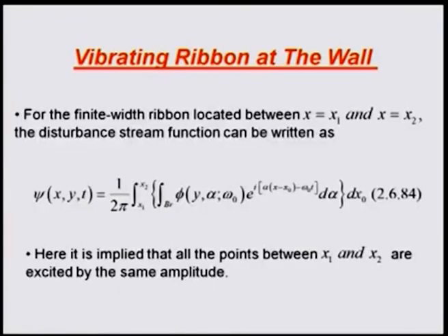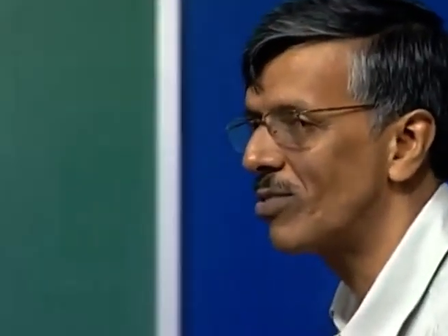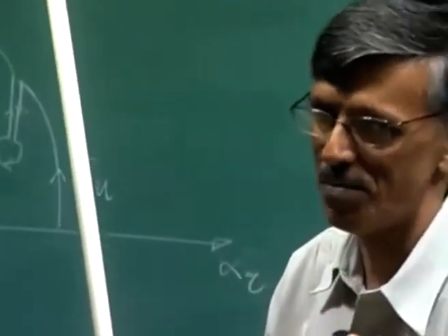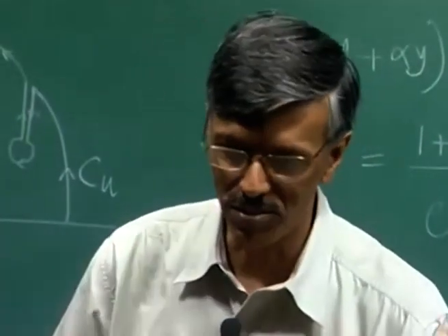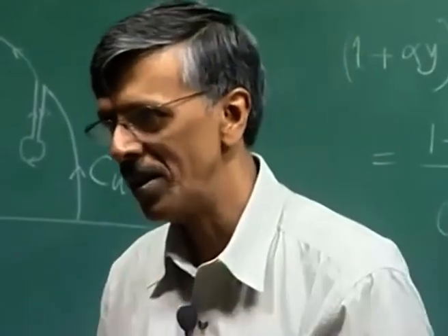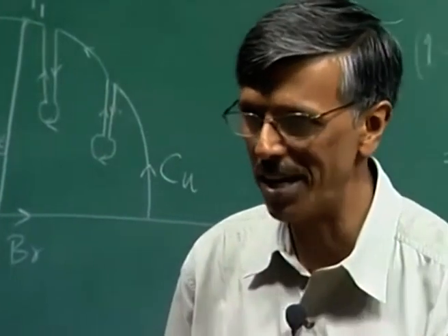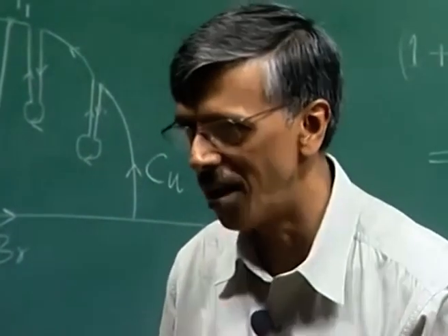Analytically it looks neat, but if I tell you to go ahead and try to do it for the solution of the Navier-Stokes equation, you will sweat. Why? Because of those discontinuities at the end of the strip. At the end of the strip you will have 0 and then a finite value, and that will excite all possible alphas, and numerically that is a disaster story.